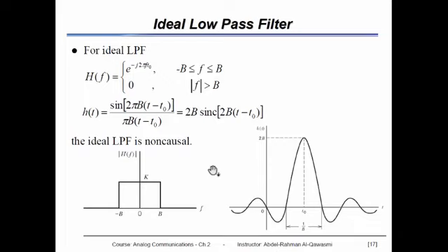So we use this sinc property, and it will give us a rectangular pulse, and you can imagine this is our A sin(πft) over πft, and this is our A in the rectangular pulse. Please refer to the previous examples about Fourier transform properties, and you will understand how we found the Fourier transform.